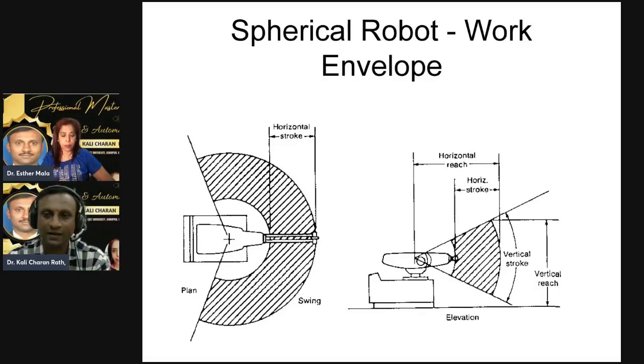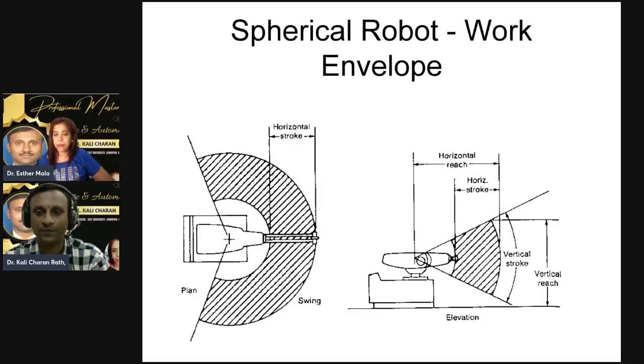Now the next is designed based upon the SCARA robot, which is particular to industries. This is the SCARA robot. Here, two revolution and one prismatic. The two revolution joints are parallel and allow the robot to move in a horizontal plane, along with an additional prismatic joint that moves in a vertical manner. You can see it at the end.